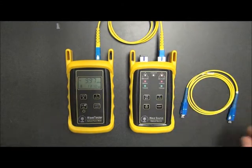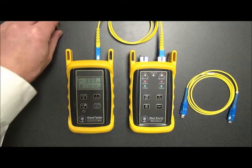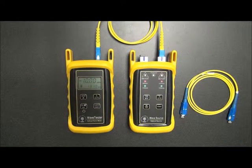Now, once we plug in, our target value is minus 10 dBm. Minus 10 dBm is where our single mode light sources are calibrated at through a single mode patch cable. In this case, we have a reading of very close to minus 10. It's minus 9.96, minus 9.7. You can't get much closer than this. So what this means is that this patch cable is okay to use for our test.